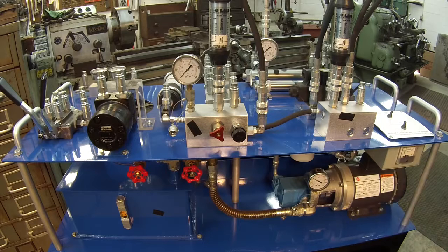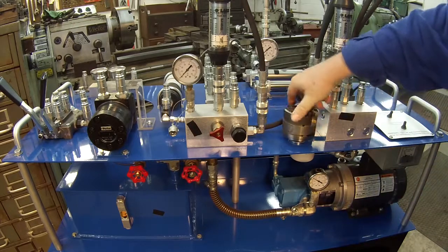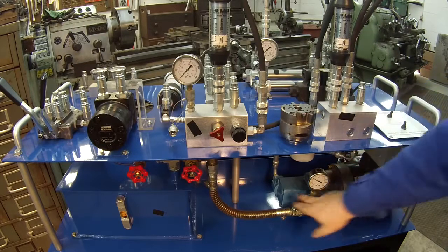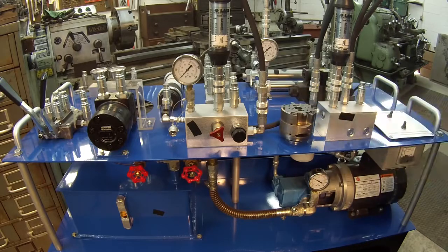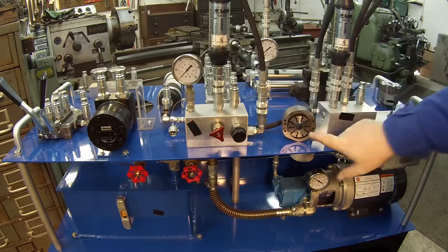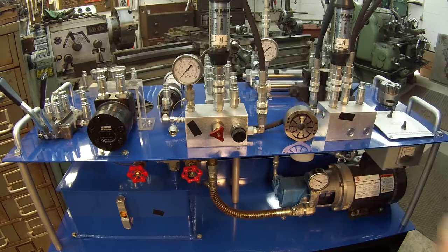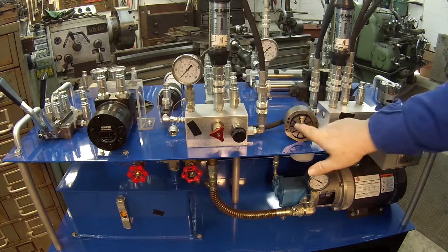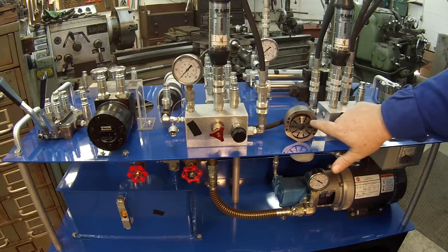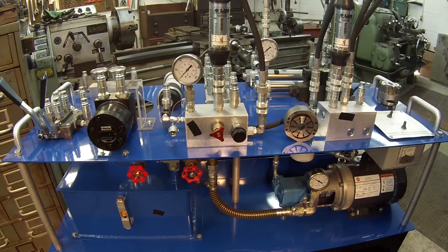So this is called a cartridge kit, and this has your vanes in it. Like inside this pump right here, you would have one of these cartridge kits, okay? And inside this cartridge kit, this little ring right here, this is your ring and your rotor with your vanes in it right here. And so what happens is that thing spins around and your vanes contact this ring right here, and that's how you pump fluid. You've got an increasing and decreasing part of this ring right here, so that's how you pump your fluid in and out of this pump.